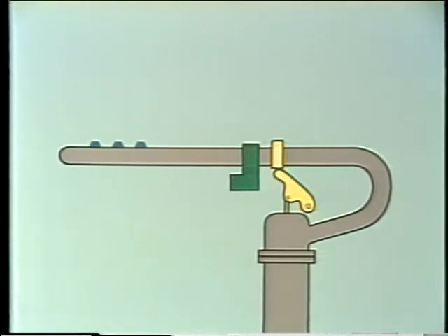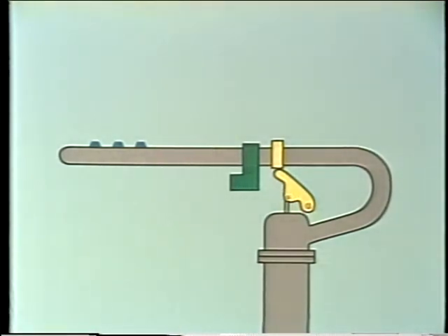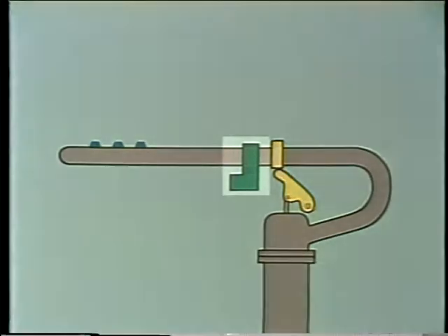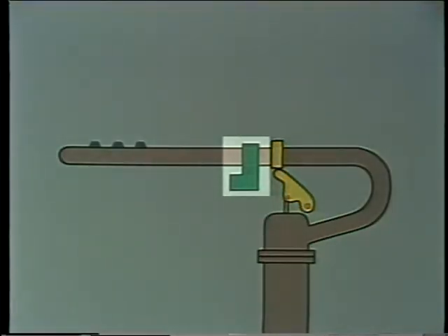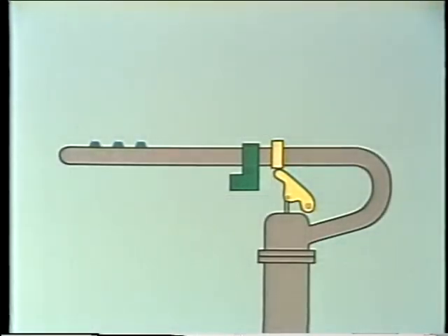The big difference is that the elements of rotating soot blowers rotate. They can direct the blowing medium over a much larger area than fixed soot blowers. In order to do this, they have a drive mechanism to rotate the element. This drive mechanism may be an electric or pneumatic drive, or on older systems, the drive may be a manual drive using a hand wheel or a chain sheave to turn the element.